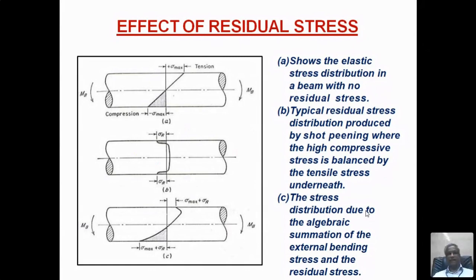And thermal fatigue, thermal cycle, volume changes from cold to hot. Thermal fatigue is nothing but low temperature to high temperature, cold temperature to high temperature. There is an operating temperature. Yesterday I told you, somebody asked about low cycle fatigue. So low cycle fatigue is from cold temperature to hot. Cold means don't think that it is 0 or minus. Even at room temperature, the operating temperature is fluctuating from 100 degrees to 600 degrees. Cold is 100 and hot is 600. So the variation, the fluctuation in the temperature, will also cause fatigue in the material.